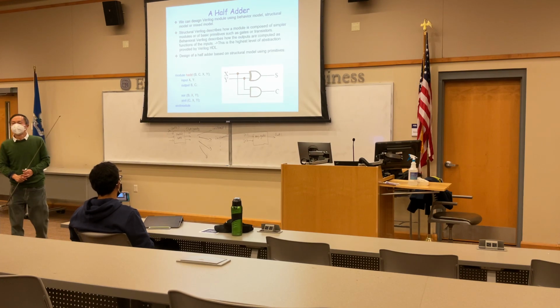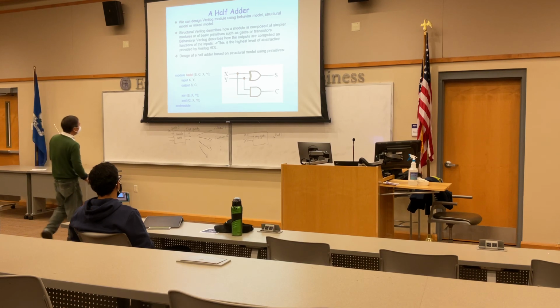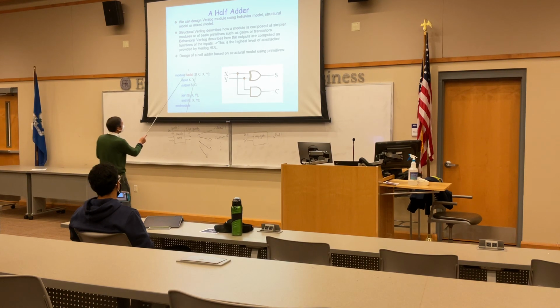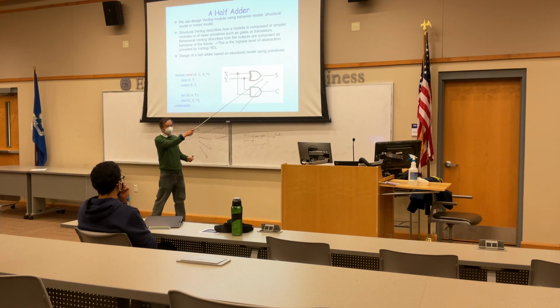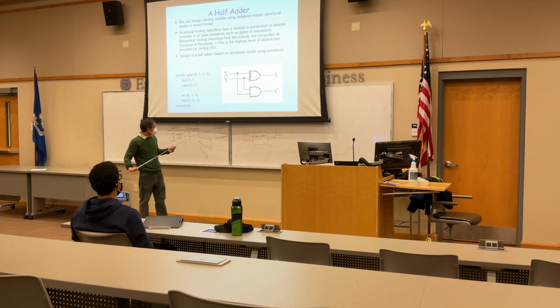So we can use primitives to construct a circuit, just designate their input-output port list, but stick with the same order as your original definition. Now, this one we define with a name. In the future, we can easily do instantiation.